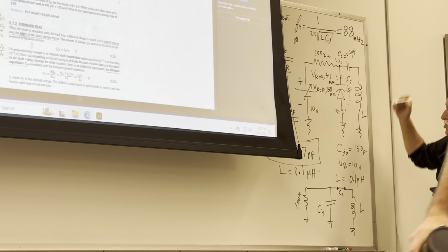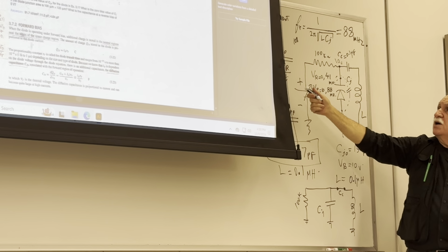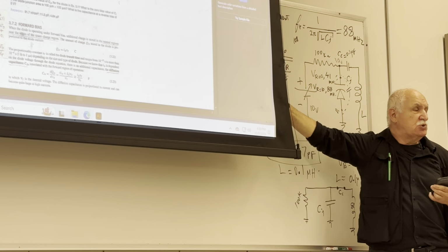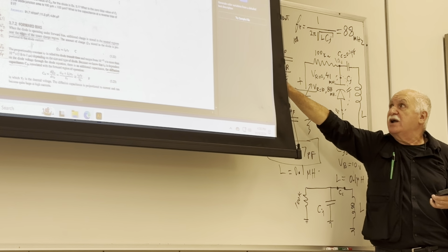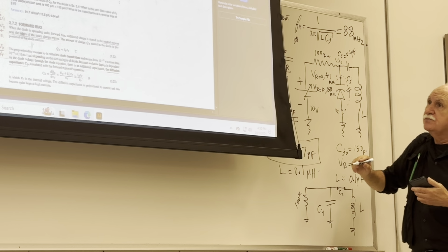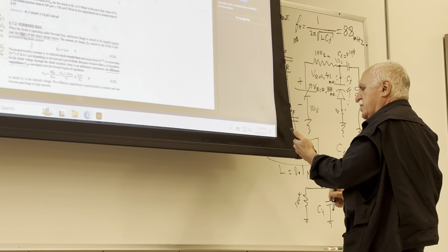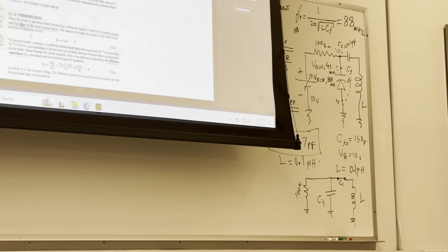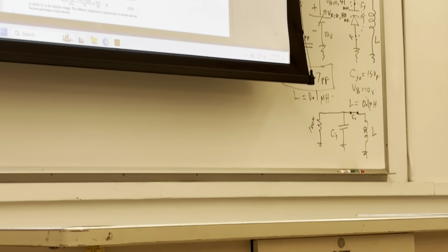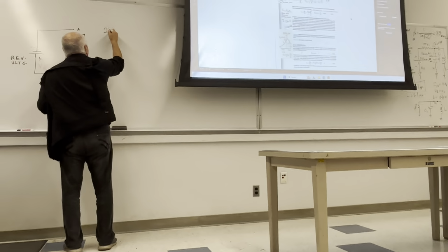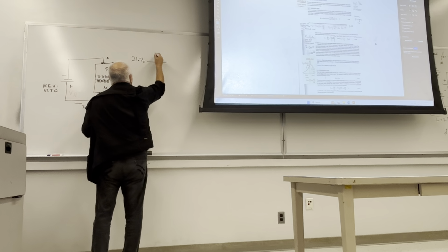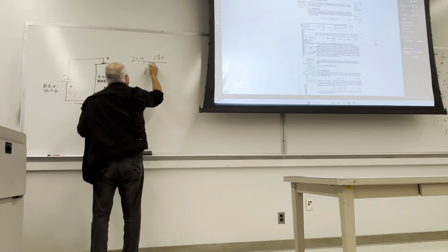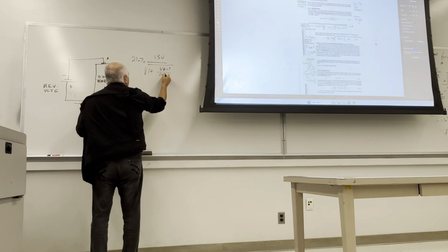I need 21.7 picofarad. So what is then the voltage you need to produce 21.7 picofarad? I will go in here. 21.7, 150, radical, 1 plus VR (we don't know), phi j is half a volt.